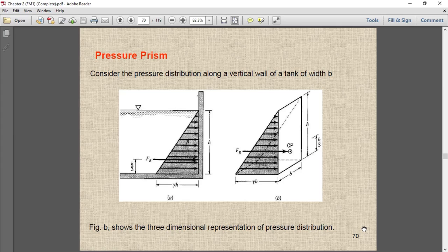And the first technique we discussed is using the formula, and we showed in detail how we calculate the pressure on the flat surface when the pressure acting on the fluid is hydrostatic, and the pressure acting on the free surface is the atmospheric pressure. So these two conditions are very important to understand.